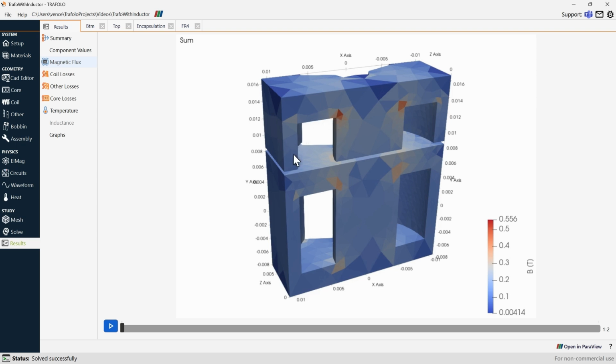However, what we are mostly interested in is the magnetic flux values in the bulk, which is between 0.2 and 0.3, meaning that our core in general is not going to saturate, so the usage of constant permeability in this case is acceptable. If we would get closer to saturation, then of course we would definitely need to use a BH curve.